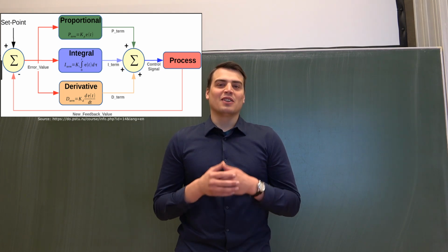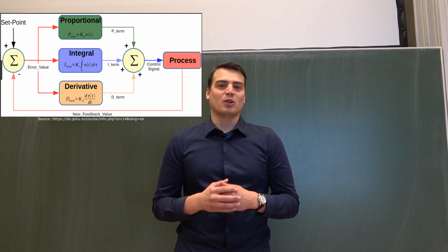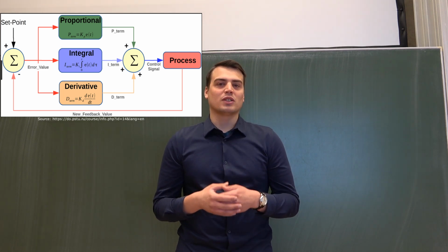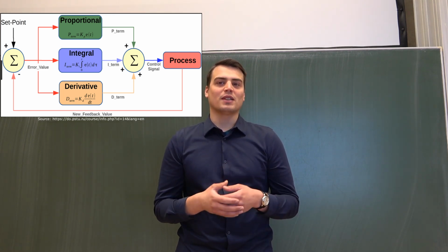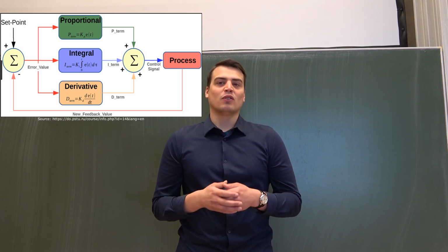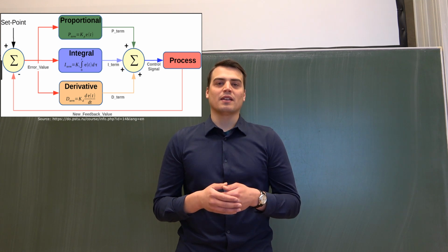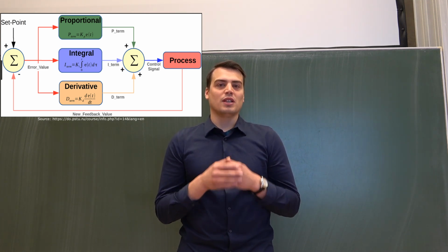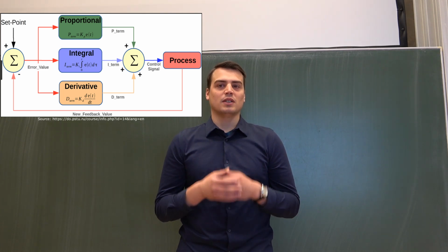It's important to find a trade-off in proportional gain, because if it's too small, then the whole system reacts slowly when compensating for this error. Conversely, if the value of the proportional gain is too high, the system will start to oscillate, which indicates that the control system is unstable.